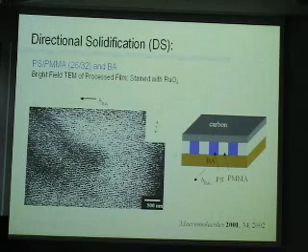We actually used a variety of examples of block copolymers. We start with polystyrene and polymethacrylate, PMMA. The ratio is about 50%. We expect a lamella-forming block copolymer. So we just did the benzoic acid directional solidification process. We found the microstructure is well organized and has a very beautiful orientation. This schematic diagram shows the orientation of this lamellae sample of polystyrene and PMMA.